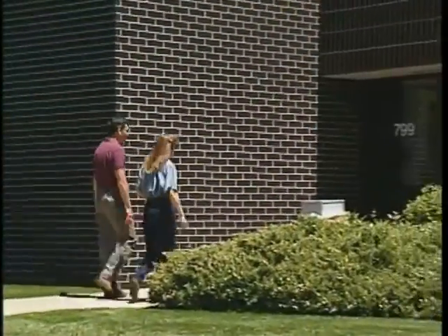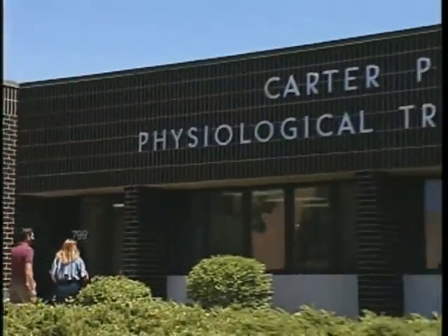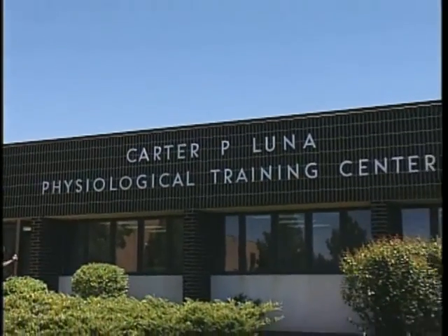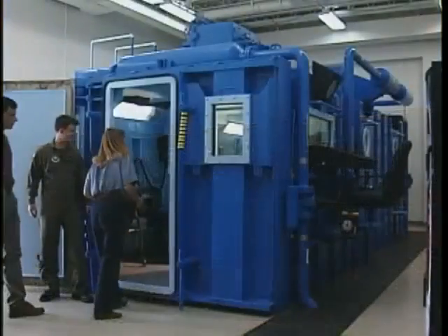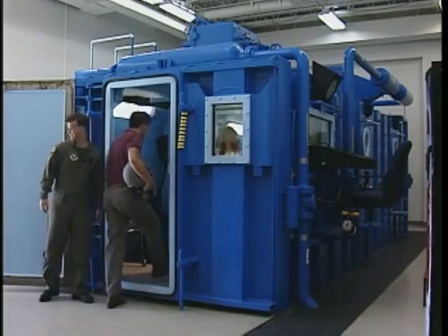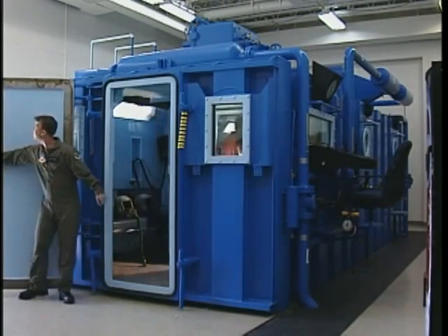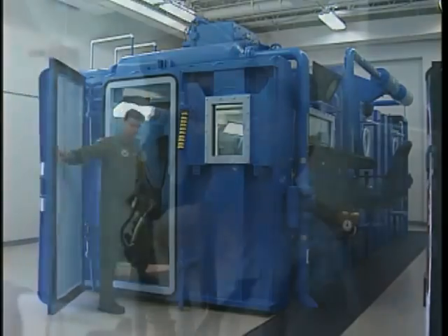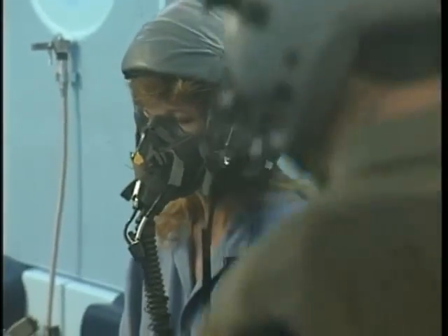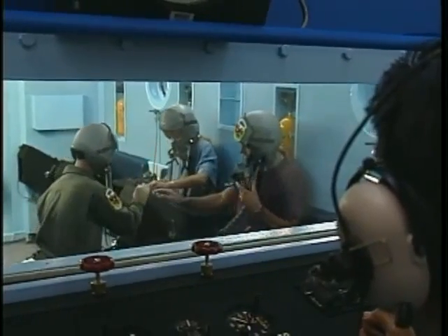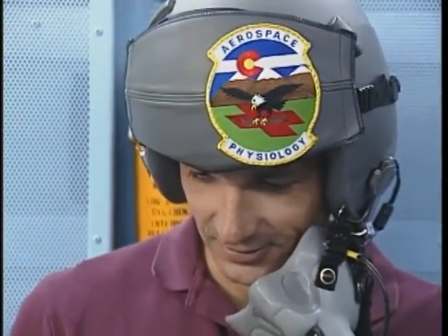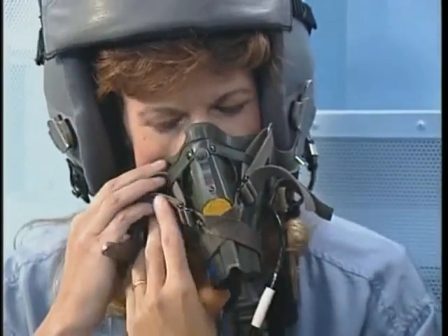To generate interest in high-altitude training, you can suggest that the pilot attend a physiological training program to learn more about the problems associated with reduced atmospheric pressure at high flight altitudes. These programs include a high-altitude flight in an altitude chamber where pilots can learn to recognize the onset of hypoxia by understanding their individual reactions to it. Applications for this training can be obtained from your local Flight Standards District office. If you have not experienced this physiological training yourself, participation in this type of program will greatly increase your instructional knowledge.